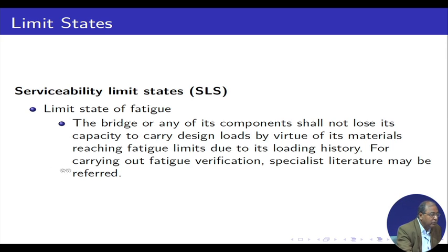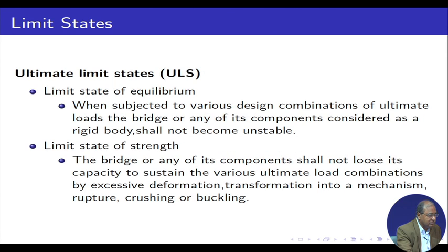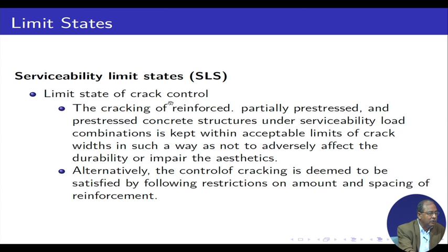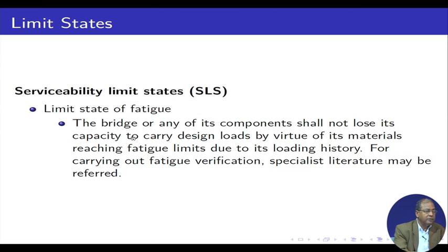I can once more repeat: ultimate limit states, there are two, equilibrium and strength. Then serviceability limit states: internal stress, crack control, deformation, vibration and fatigue. So, these are the things available, and we have to check all of them.